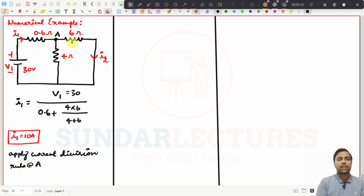Then if you want to find the current in this branch, which means I through 4 ohms, that is equal to the total current, 10 amperes, into the opposite resistor, 6 ohms, divided by the total resistance, which is 10. Then this 10 will be cancelled out, and I through 4 ohms will be 6 amperes.